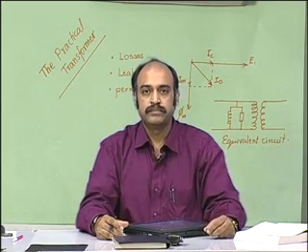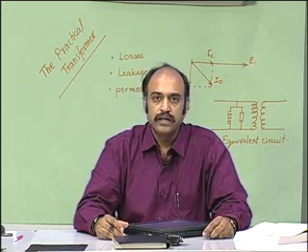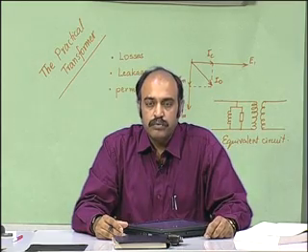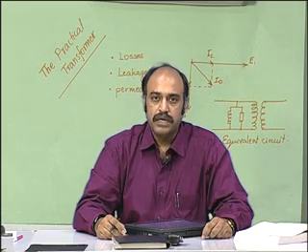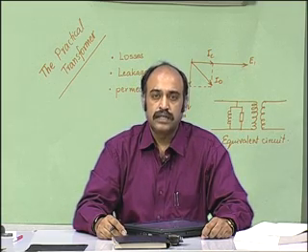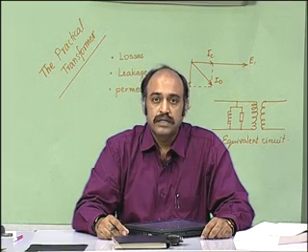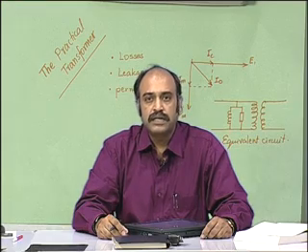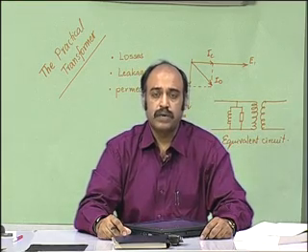Hello everybody. In the last session we were discussing the power transformer. We saw that the power transformer could be used for many applications, one of them being isolation, the other is for step up or step down, and the third one is for impedance matching. In the case of isolation transformers, the turns ratio is normally kept at 1:1.